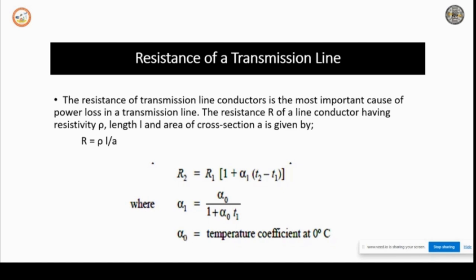The effective resistance of a conductor is given by R is equal to P by I squared. R is equal to rho L by A. When the distribution of current in a conductor is uniform, then the effective resistance is equal to the DC resistance of the conductor. Got it? This DC resistance is given by rho L by A, where rho is the resistivity of the conductor, L is the length of the conductor, and A is the cross-sectional area of the conductor.